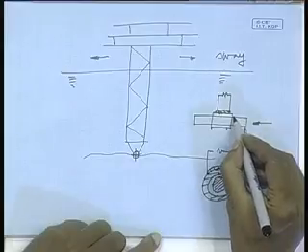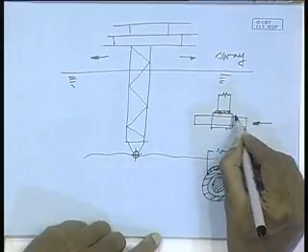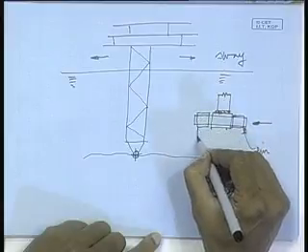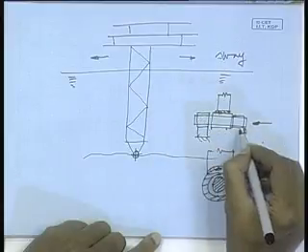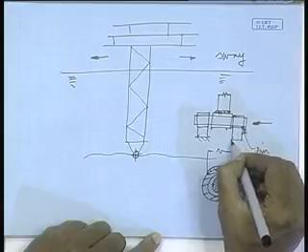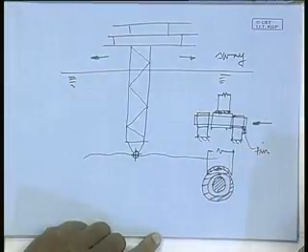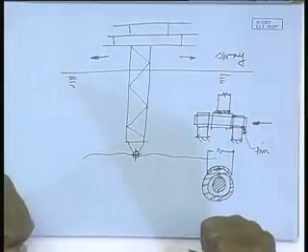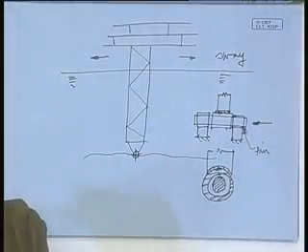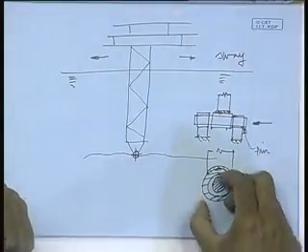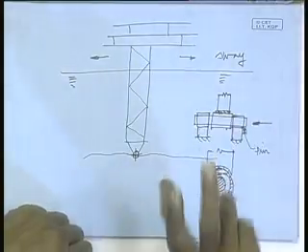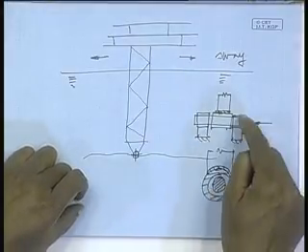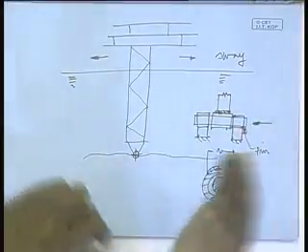And then you have the other, and this one is grouted at the seabed. So either the pin is rigidly clamped to the seabed, and over this cylindrical part the middle part moves, or the pin is rigid to the cylindrical part, and these two bearings are free to rotate.